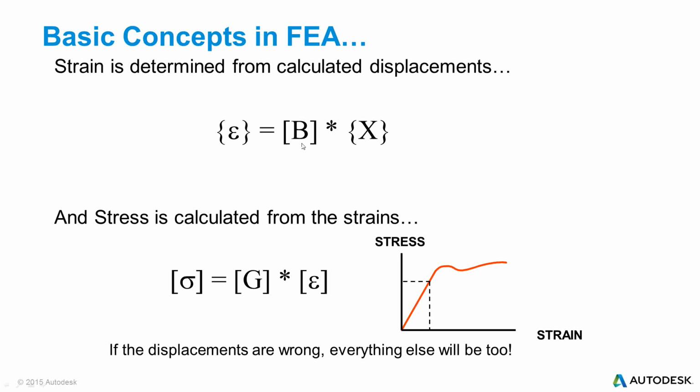This B matrix is usually a very, very complicated matrix, especially if you're using quad elements or hexagonal elements or P elements. The B matrix is the element formulation for the most part, and every finite element code guards how they calculate those B matrices very carefully, because it's sort of their proprietary edge over the competition: we calculate a better B matrix than someone else. They can use that to brag.